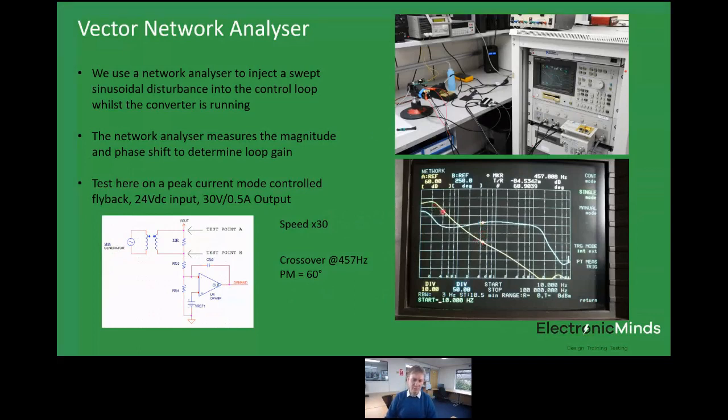And we have a nicely falling, a nice 20 dB per decade roll off, which is exactly what we want. You get some funny stuff happening up at high frequency, because remember, this is measuring up to 100 kilohertz. We've actually passed through the switching frequency of the converter at that point. So the data beyond half the switching frequency is largely meaningless. We're really interested in what's happening down at low frequency.